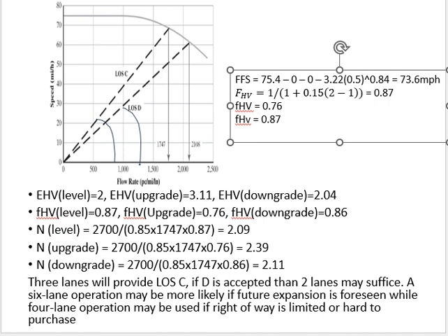On my y-axis the first point is free flow speed. What is the free flow speed? This much. So I know the first point. Clear? Next thing is we have to draw a straight line up to breakpoint. From free flow speed, I will draw a straight line up to my breakpoint. What is my breakpoint? For breakpoint, I have an equation.